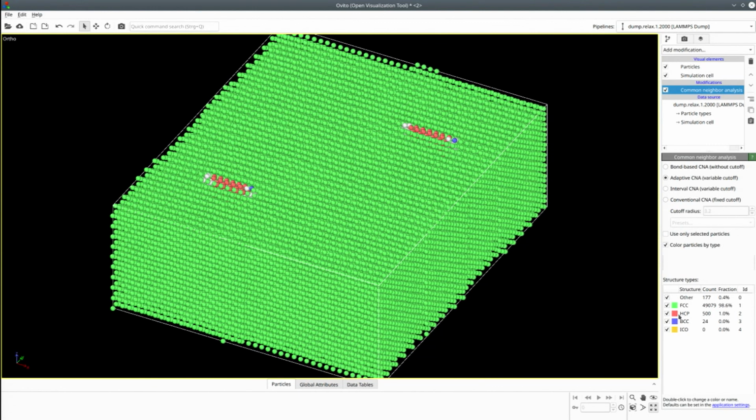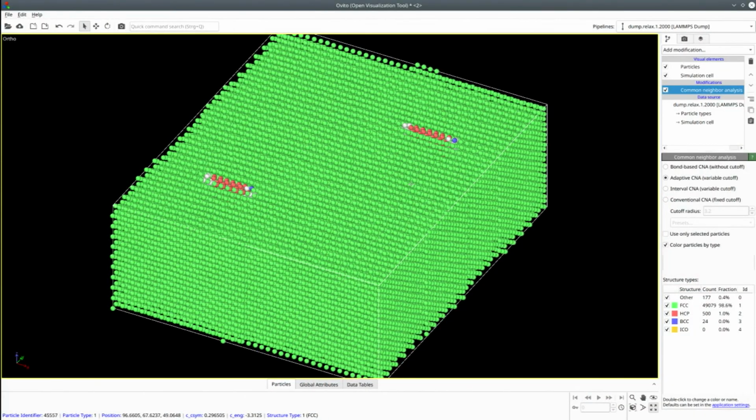And that's just a stacking fault in a split partial dislocation, or in a complete dislocation which is split into two partials. I use the dipole here, and I'm not sure. I think I put the dipole already here in this 45-degree configuration. And this should be also the stable configuration for a dislocation dipole.